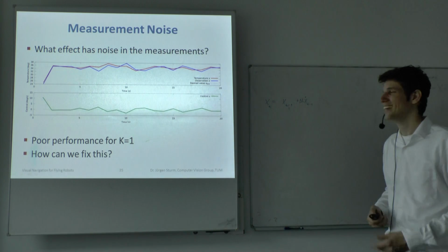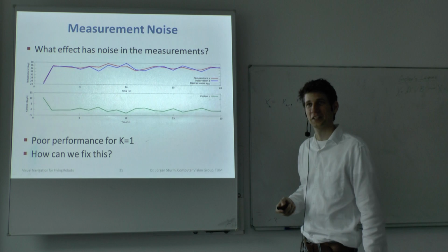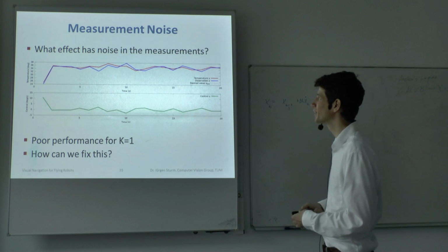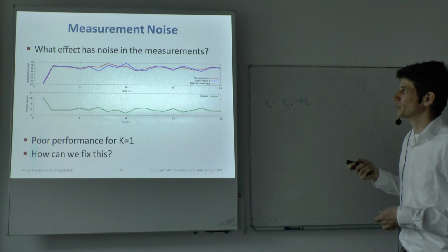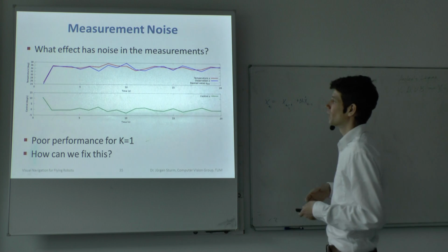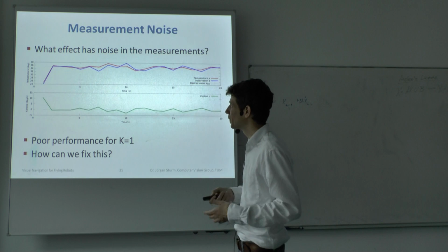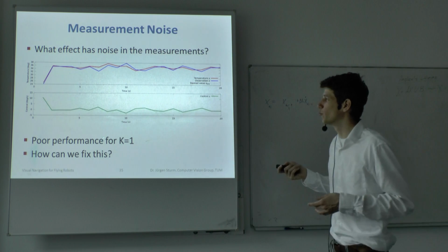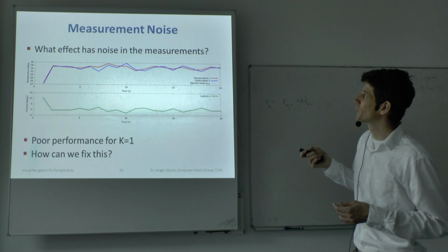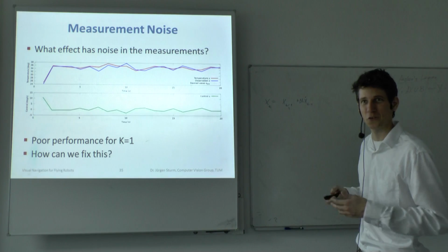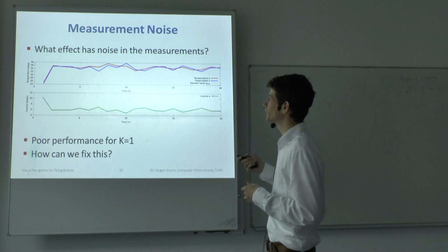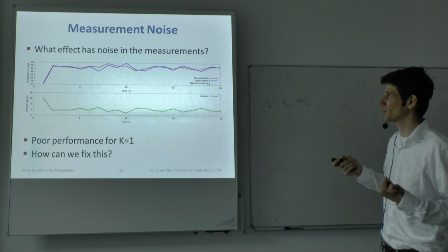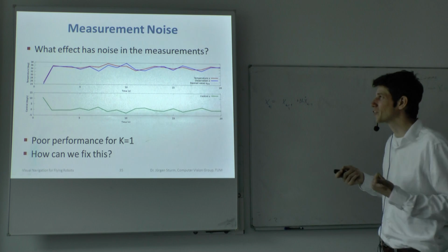Unfortunately, there is always some noise, both in the temperature that your apartment or that your shower gets from the heater, but also in the temperature that you measure. And then if you do that, and then you have a gain of 1, then the temperature here will change strongly depending on the noise. So it could get very hot or very cold, which is one thing. You're not actually close to the optimal temperature that you want to achieve.